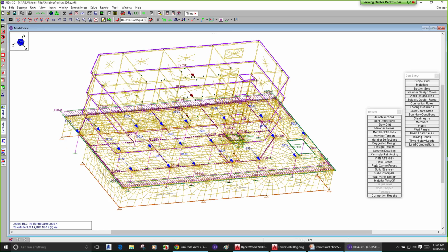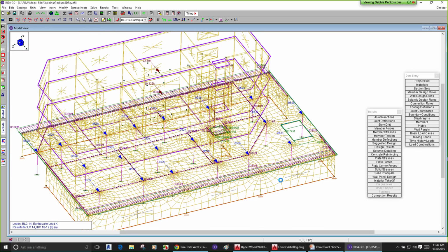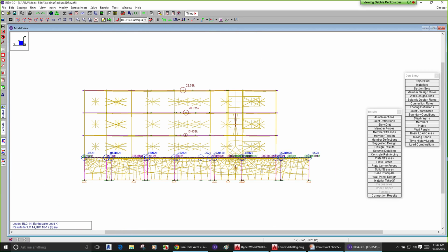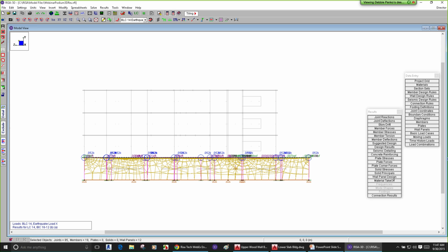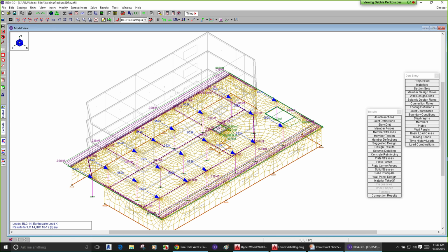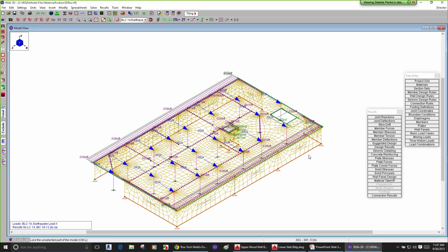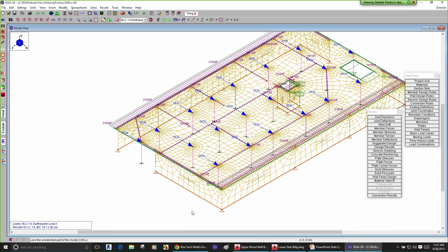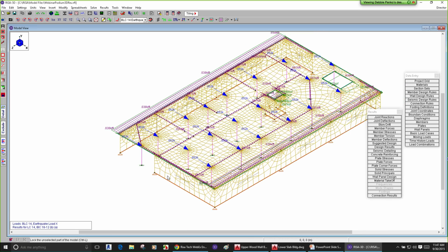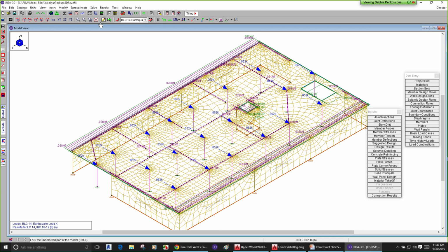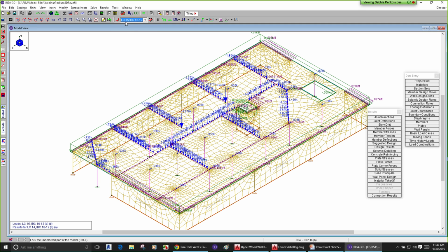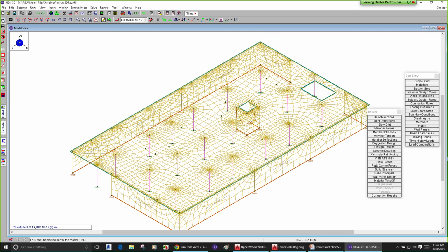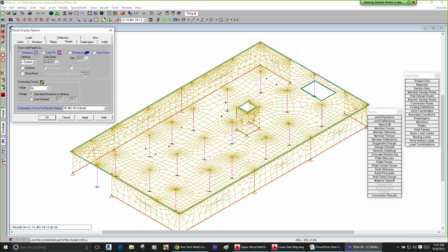So you'll see here, this is our semi-rigid diaphragm. I'm going to actually show this a little differently here. I'm going to turn off the top of the structure, and I'm just going to select the lower portion of my structure, and I'm going to look at this right here. I actually use the lock button, and then it allows me to turn off that upper structure for a second. So you can see I'm just showing the deflection on this lower level as we apply those loads. I'm going to go ahead and show maybe load combination 15. So this is this load combination. As we apply that, you can start to see here, there's 14 and 15, what's happening in the structure.